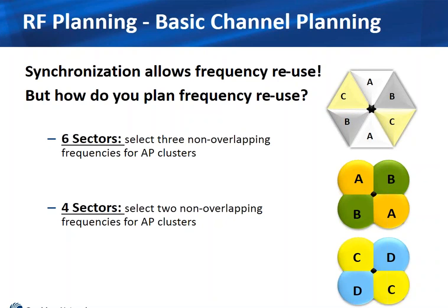This would fall flat as far as the interference that the two access points using the same frequencies on the exact same tower structure would cause. When they're transmitting unsynchronized, you will have significant, severe impact to the overall throughput that these radios are able to produce.